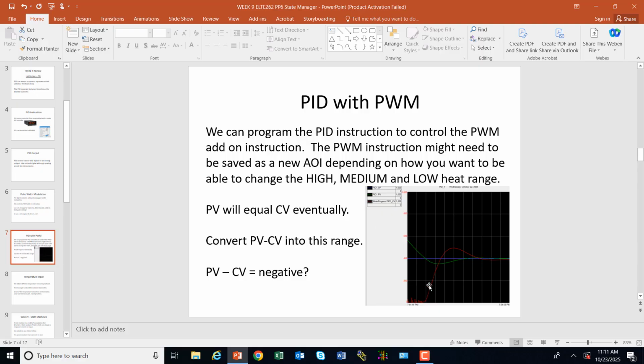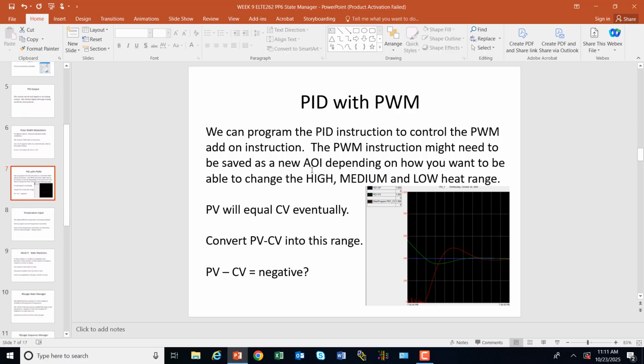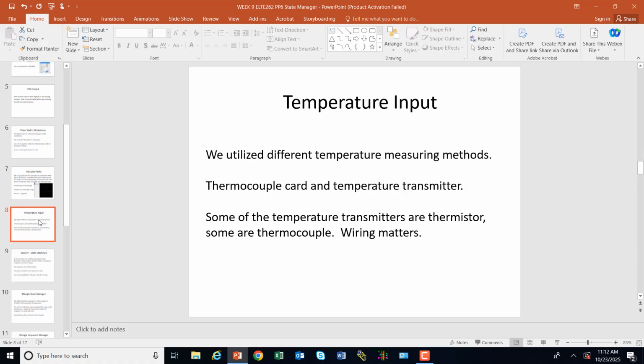and you can probably put some numbers in there to get this to converge relatively quickly and smoothly without loading up the integral part of this, because when that integral loads up, this might mess us up a little bit. If we get too much integral on here, it might never let this control CV settle down like we want it to. So that's what we're looking for on the last one. You have to modify your pulse width modulation instruction a little bit, if that makes sense.